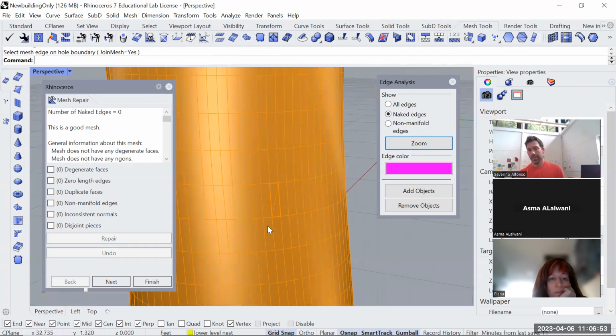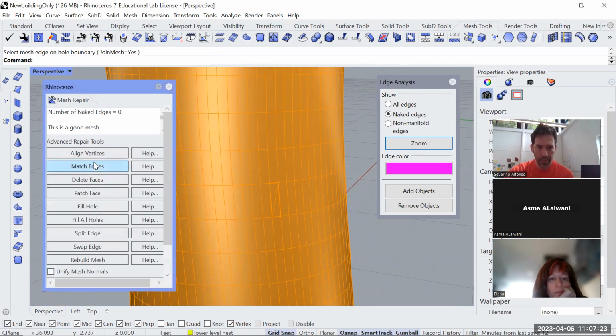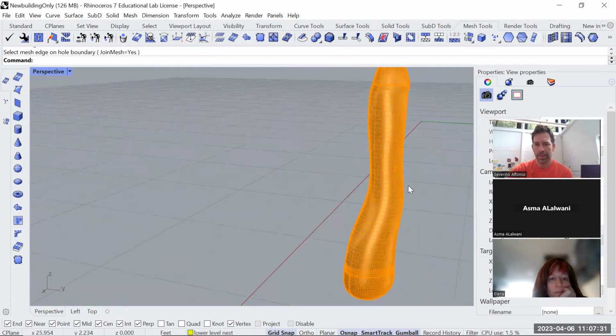So it doesn't matter for my model if there are openings or not. It's just going to be volumes in space. I mean, if you did an offset of the surface, hopefully there's no big problem. But if you have any problem when you're doing this, let me know, and I'll sit one-on-one. But in theory, if it tells you here is a good mesh, you should be in good shape. Anyway, next, you can do fixing problems. You can fill holes here. You can do split edges. So there's a bunch of things that you can do through this system. You will solve your problems.